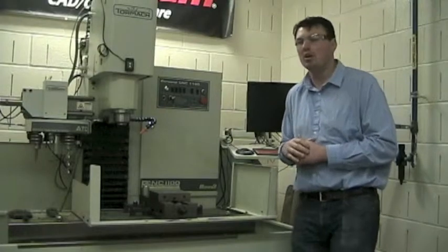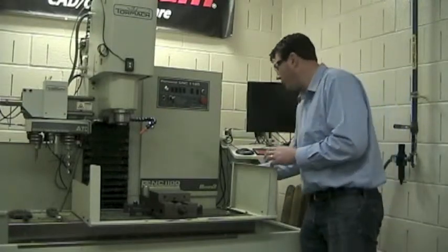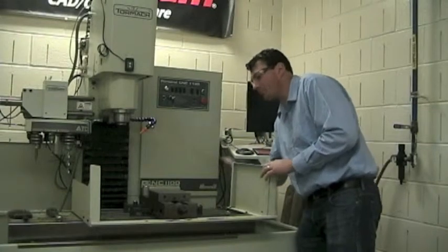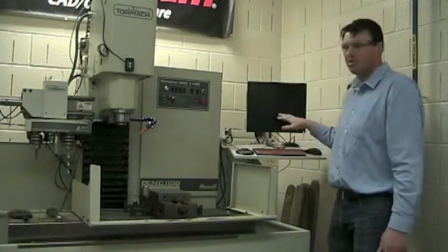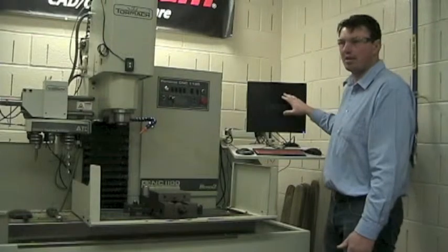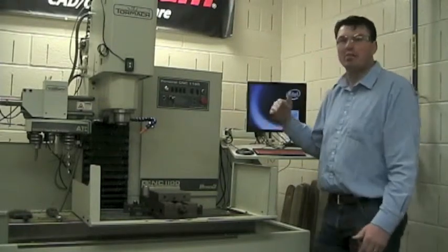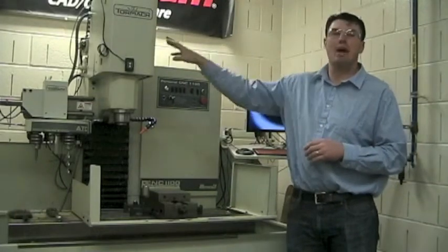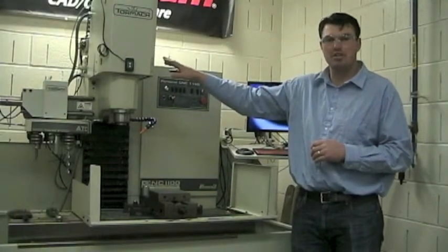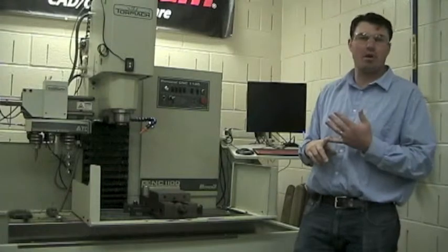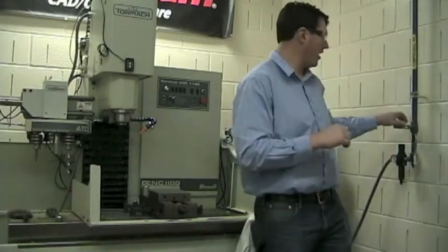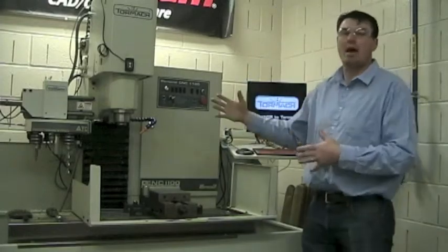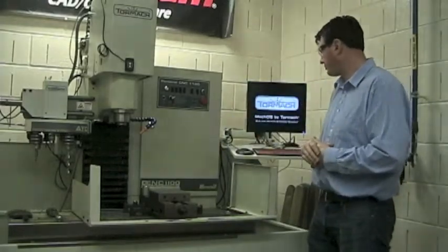So to get started, I'm going to flip the main power on the machine, which is on the right hand side. And once I throw this switch, my controller software is automatically going to boot up. Now whenever we run this machine, it's important to understand that it is a pneumatic system that controls the tool changes. So we have to have our air compressor on, and we must have our air line opened up going to the machine so that there's power to the pneumatic system.